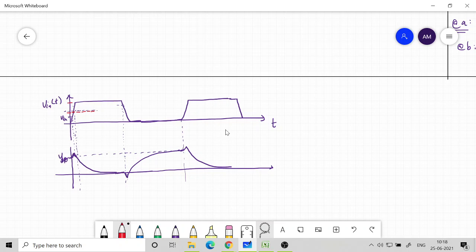So this is VDD, take 50 percentage of that, and wherever the line meets, you drop a perpendicular, and then also take the 50 percentage of the output. Okay, so this is an alternate way of defining.